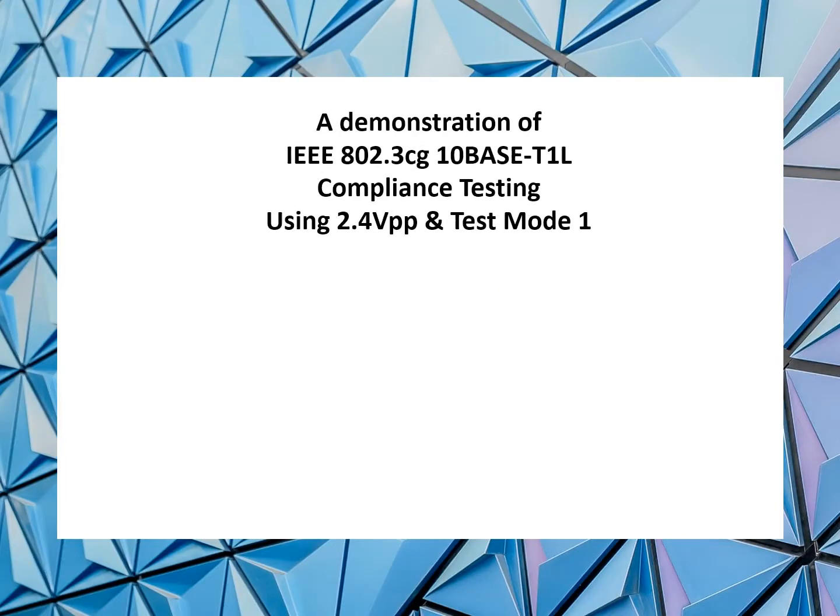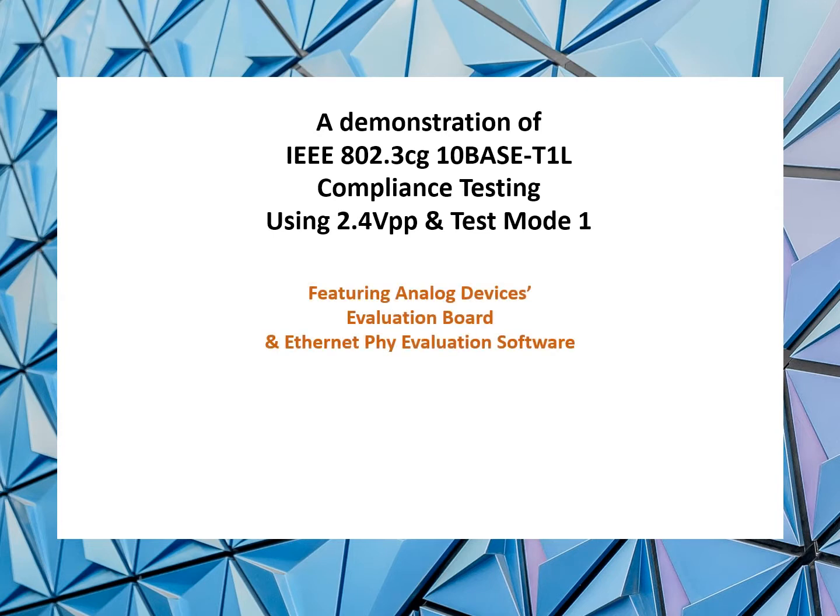Welcome to a demonstration of IEEE 802.3cg 10BASE-T1L compliance testing using 2.4 volts peak-to-peak and test mode 1. This demonstration will feature Analog Devices evaluation board and Ethernet PHY evaluation software with Telebyte's digital analyzer, probe, and software.